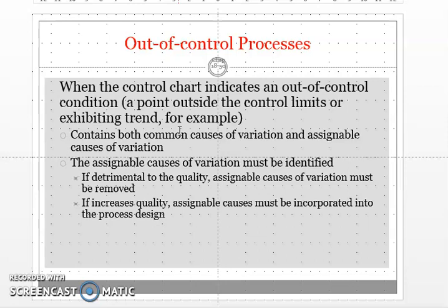The purpose of the control chart is to identify whether the process has assignable cause of variation. Through readings or calculations and the nature of the graph you are observing, you have to take necessary precautions, because the variation is not a natural variation.